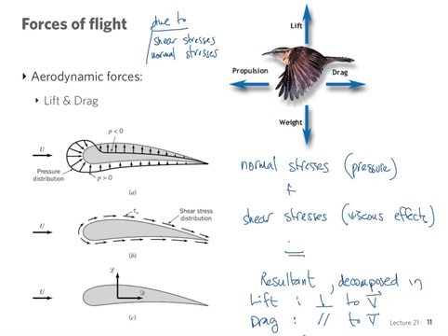Now, if you think about this picture of the aerodynamic forces being produced by this distributed shear around the wing, then of course, both P and shear stress will vary in magnitude. Pressure will also vary in direction. Well, they both vary in direction with respect to any reference frame. And so their integrated effects produce a resultant force, and you can see that it would be very hard to actually know the shear stress and pressure to be able to obtain the lift and drag.